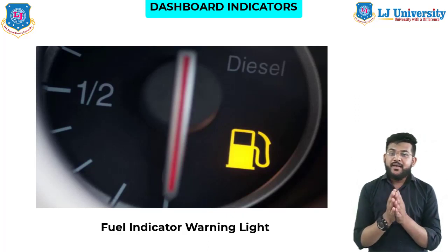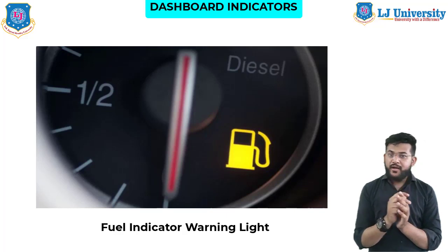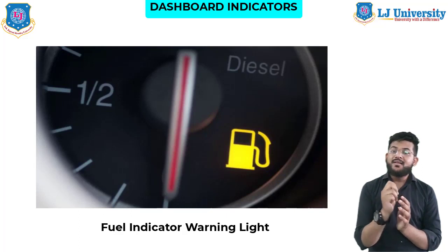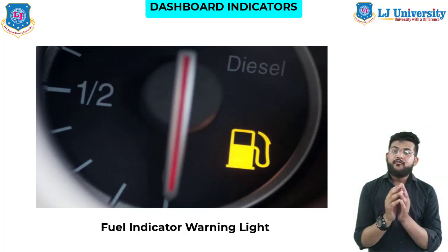Diesel engines are quite different from their gasoline counterparts. In our vehicle, inside the fuel filter there is a fluid level sensor, which helps keep track of the amount of water that has been collected. If the level starts reaching the maximum capacity, the fluid filter light will turn on, asking you to empty this filter.